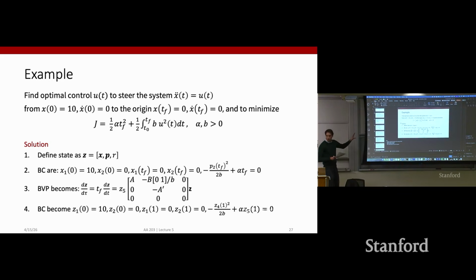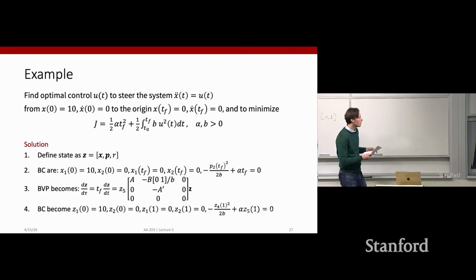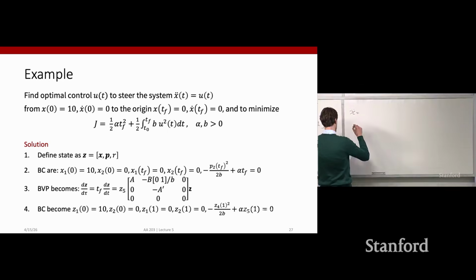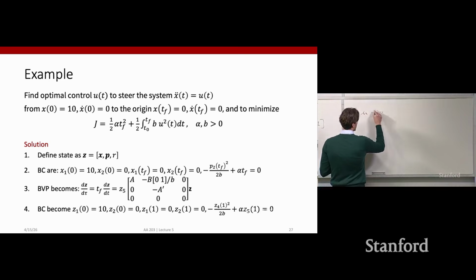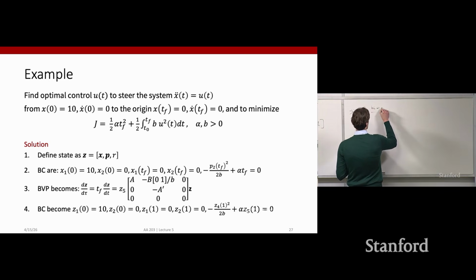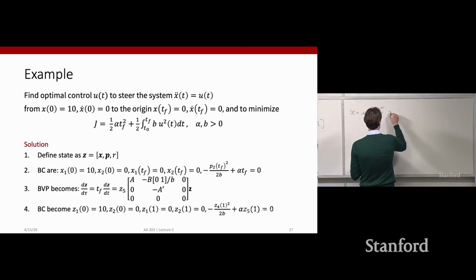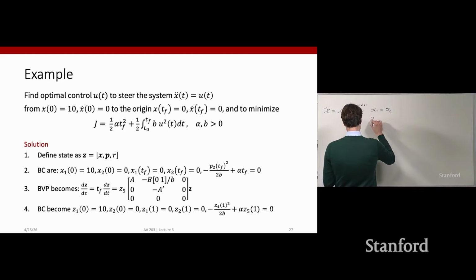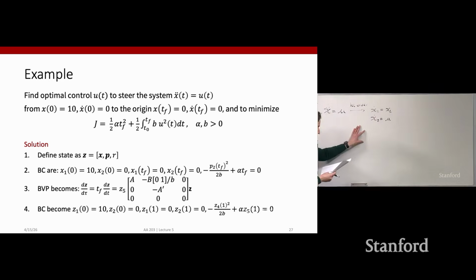And so if you remember, to solve this, we applied our classical strategy. So we derived the optimality conditions, which entails, first of all, taking our system, which in this case is a second order system, and writing it as a first order system by augmenting with one additional state variable. So x double dot equals u essentially becomes x1 dot equals x2, and x2 dot equals u. Then once we reformulate it as a first order system, we could apply our optimality conditions.